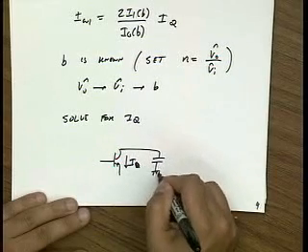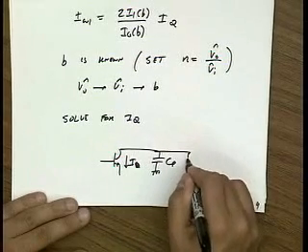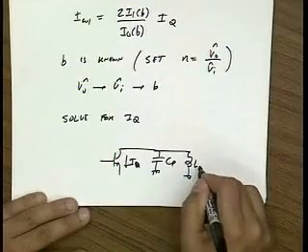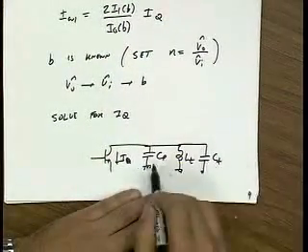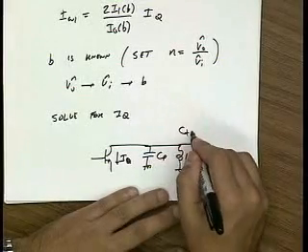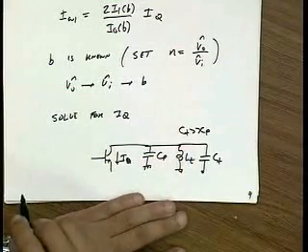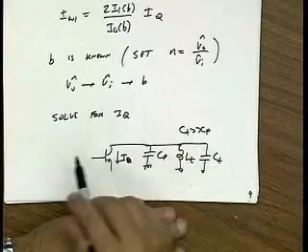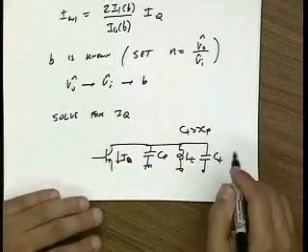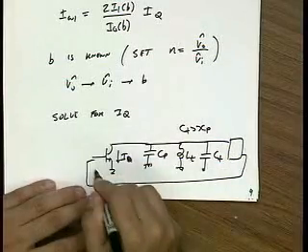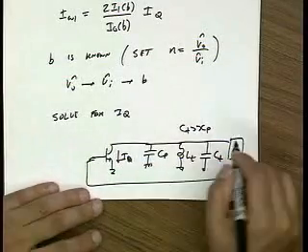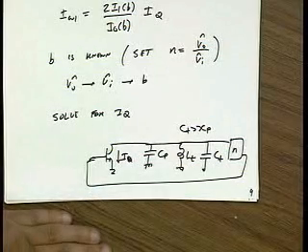There's going to be some parasitic capacitance here. I'm going to put in my tank, my inductor. I'm going to add some tank capacitance basically to dominate over the parasitic capacitance, because the parasitic capacitance will vary a lot over process. And then I design my feedback network, which is the N factor.